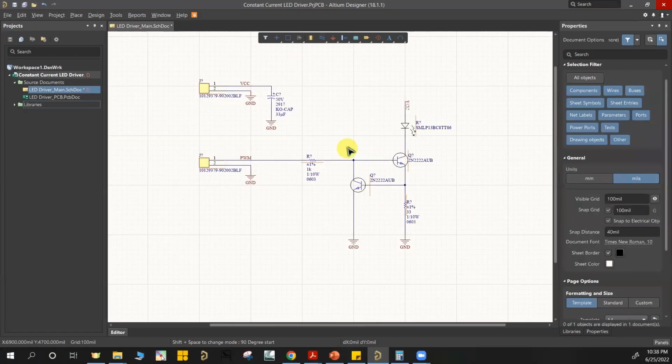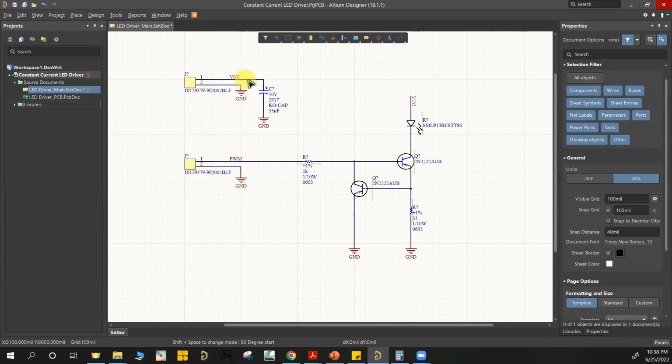So now that's pretty much the circuit. It's pretty much done. We have our input cap. We have our LED, transistor, current sense, the transistor that controls the base of the main transistor to ensure constant current, and this base resistor that, if it's connected directly to a microcontroller, is not really necessary, but we put it, again, to limit the current through the base of this BJT.